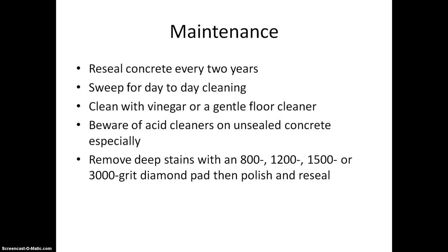And then it usually takes about 7 days to completely cure. I didn't mention that, but maintenance. You need to reseal concrete every 2 years in very low traffic areas. In high traffic areas, you're going to want to do it every couple months, but I have some videos on that. Sweeping for day-to-day cleaning.